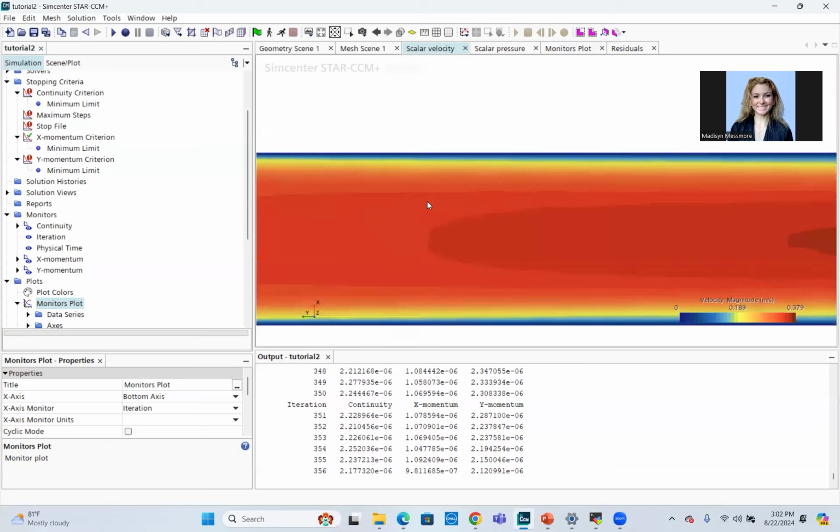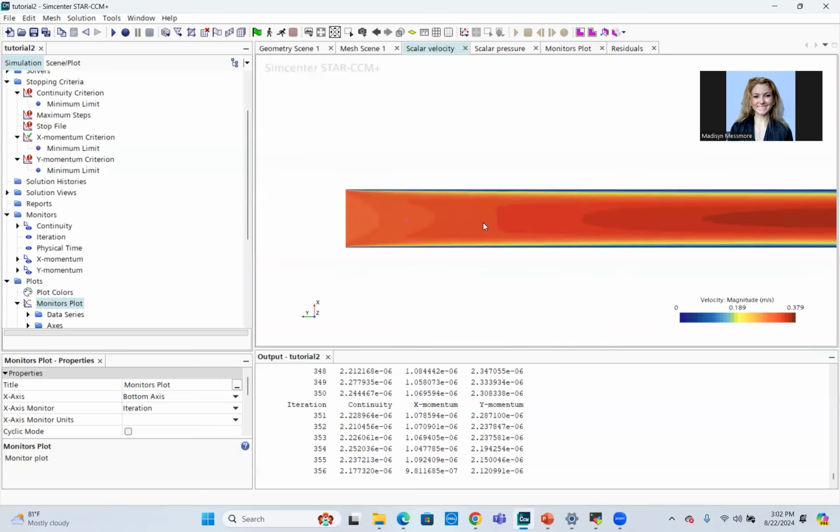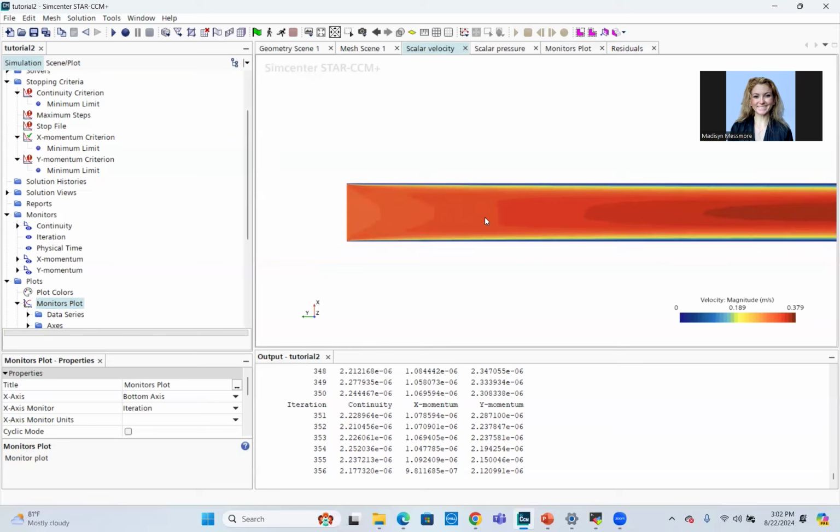Okay. So do you guys now remember that cute little graphic I was showing you before where you had those profiles? Do you kind of see how it starts off kind of flat-ish and then it gets more parabolic? Now it starts to look inverted, but that's the coloring. Effectively, why it becomes that more and more parabolic shape is because you have these walls, and it's slower because your wall isn't moving. Everything near the wall, in the boundary layer, is wanting to stick to the wall.